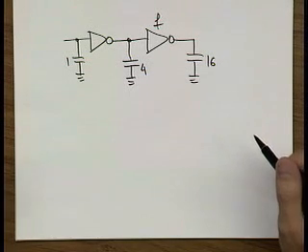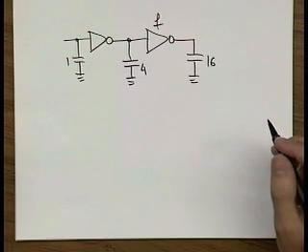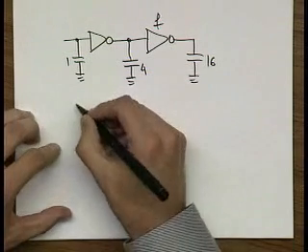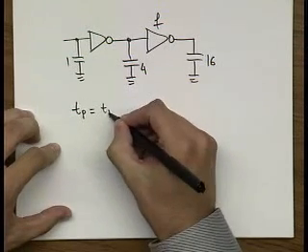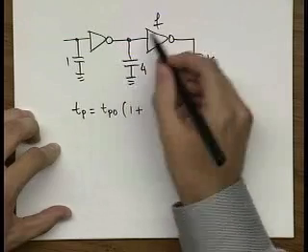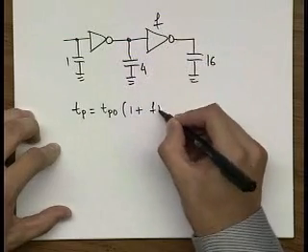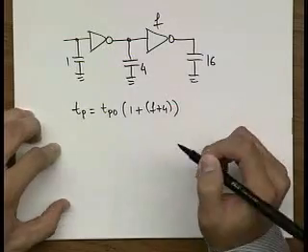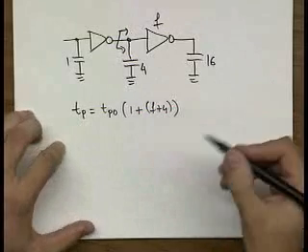So if I ask you, for example, in this case, if the problem is, let's minimize propagation delay, what are you going to do? The correct methodology is, you just write down the propagation delay expression. So for the first stage, you have 1 plus, and then you have basically f plus 4. That is the load looking into this node.